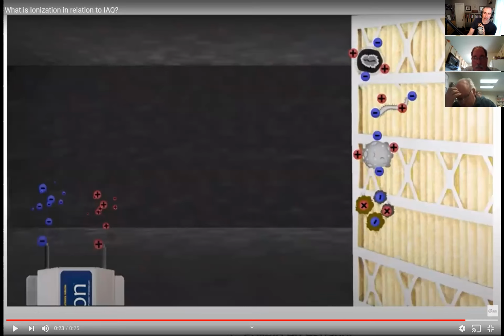Commercially, there are upper room applications, which I'll show you in a bit, that deal with large, wide open spaces. So that's specifically per Chapter 62, they actually have images in there showing upper room applications. Those are based on convective air. I have to explain that a little bit differently. But again, as long as you have a UVC wavelength bulb in an upper room design product, you're applying UVGI technology to that wide open upper room space.